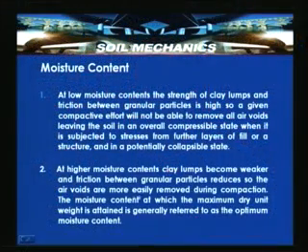So, at high moisture content, clay lumps become weaker and the friction between granular particles is reduced, so the air voids are more easily removed during compaction. The moisture content at which the maximum dry unit weight is attained is generally referred to as the optimum moisture content. This we have defined earlier, and we are defining it once again with respect to a factor, the moisture content.